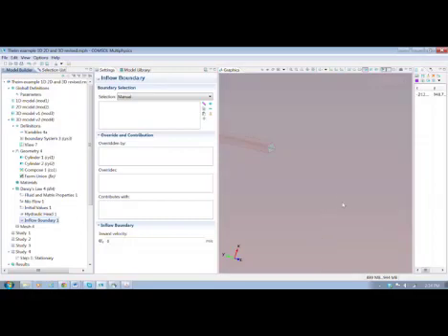For the inflow boundary, it's a little bit tricky to select them. We have to select these 4 boundary surfaces. And so the way to do it, I think, that will work best is to highlight this upper surface and then remove it. So now we can simply click on these 4 surfaces directly. So we're hiding that upper surface, the top of the disk. So we select them, and then we just make the boundary flux. I think we had a variable that was called well flux that was calculating that.